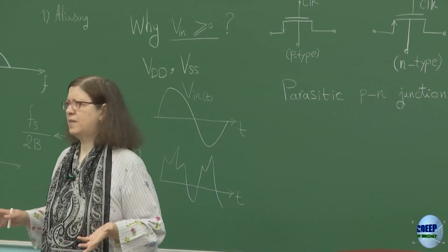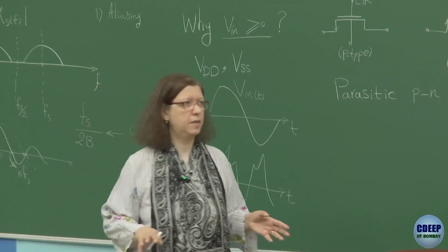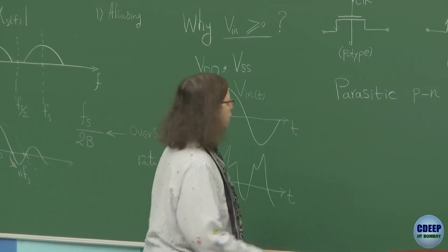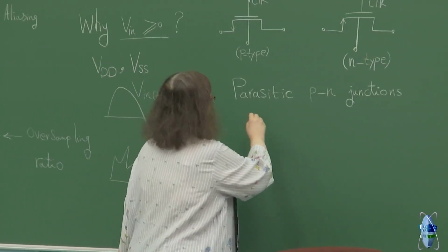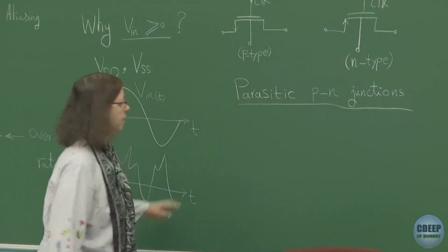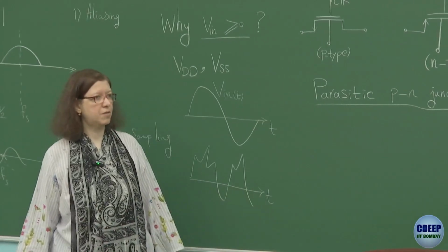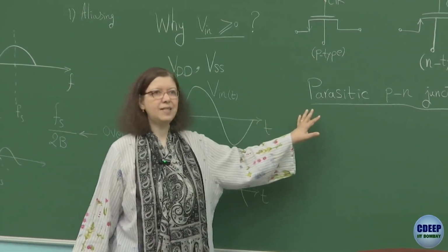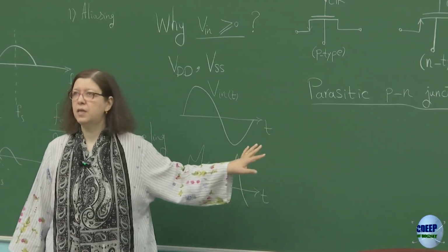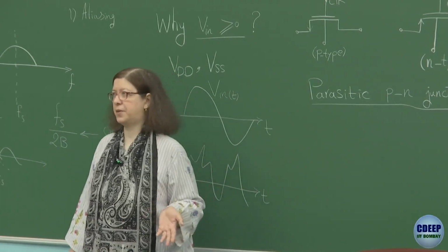No matter what the technology is, whether it is SOI, FinFET, or planar MOSFETs, in all of them we have one thing which is a fact, and we need to be careful about that. In these technologies, you have parasitic PN junctions. To operate the circuits correctly, you need to make sure that these PN junctions will not create any problem in the real operation of the circuit.